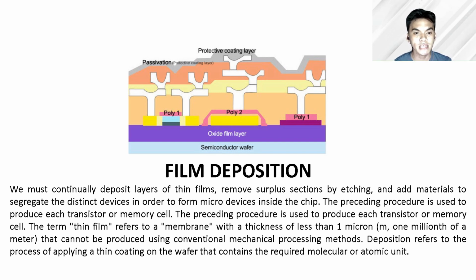There are two main etching methods, depending on the materials used. Wet etching that uses specific chemical solution for chemical reaction to remove the oxide film, and dry etching that uses gas or plasma. So what is wet etching?